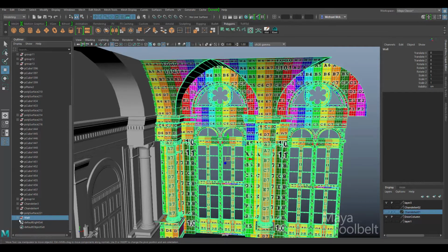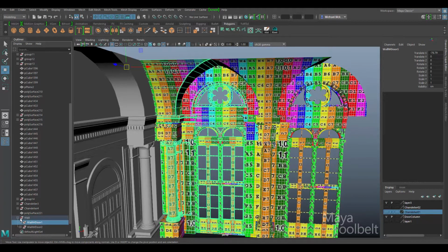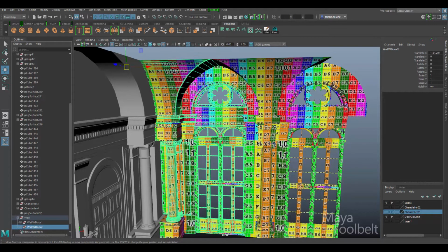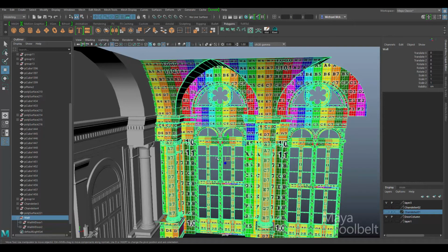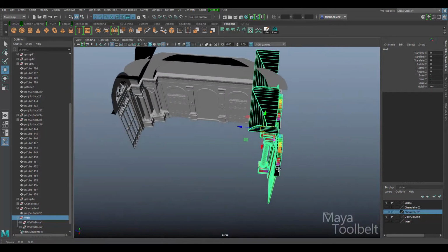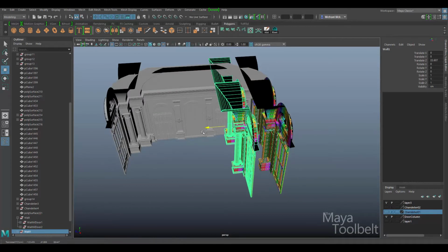And within the wall group, I have both these two groups, which I'll clean up in a little bit. I want to have all these pieces over here to be inside this group, so that's not spread out between two different groups. But with this wall group selected, I can use that and duplicate it. So Control D to duplicate it, and we can move it over here.